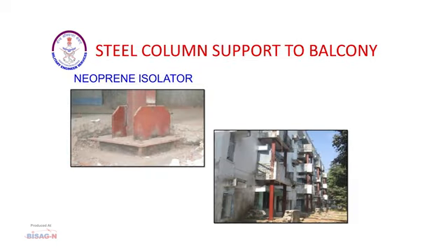In our station, we had an incidence of one balcony falling from the top, and on inspection we found that 8 balconies are showing similar signs of distress. So we provided vertical supports with neoprene bearings so that it only transfers vertical load, not movements.